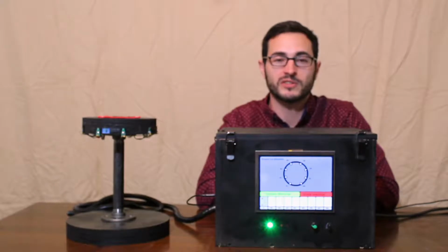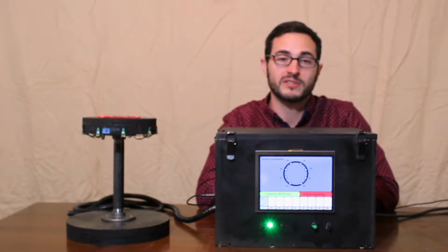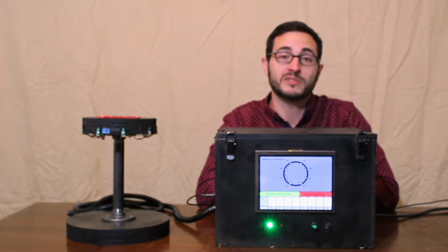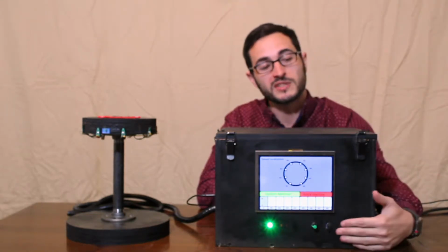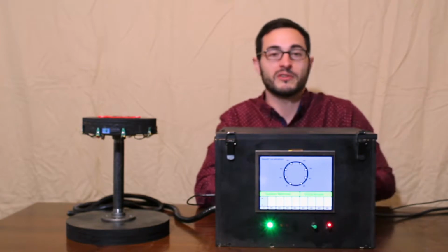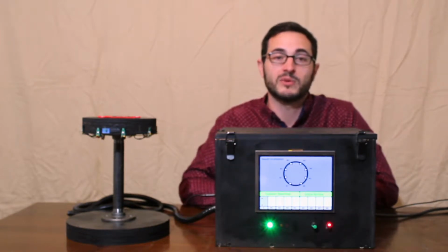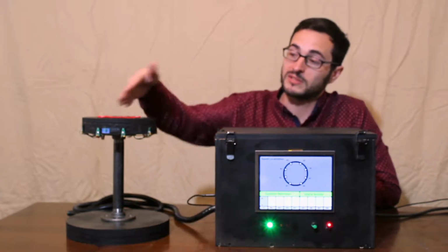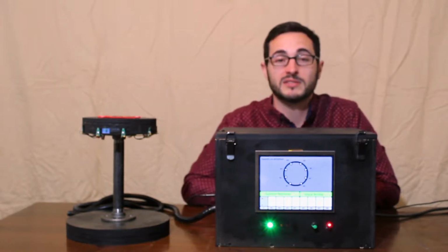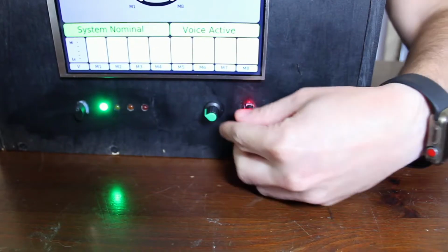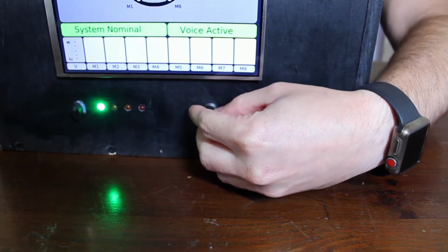To use the voice function of our system, the user activates the communication toggle switch. The communication toggle switch is a double pole, double throw switch, which passes the voice signal to the audio mixer as well as sends a voltage signal to the Raspberry Pi for the display. When the switch is activated, both the user interface and the red light on the LED will indicate that the microphone is live. The microphone used to pick up the sound is mic 8 of our array and passes to the speaker. The volume knob can be turned from low to high.